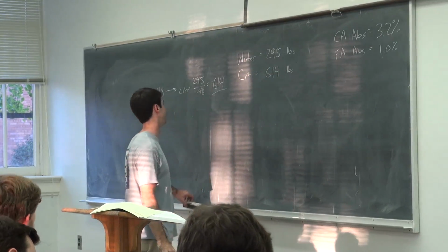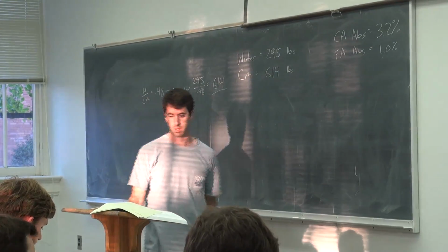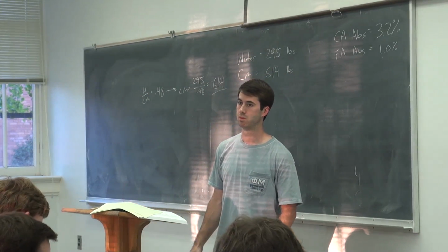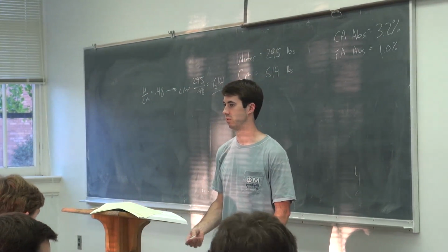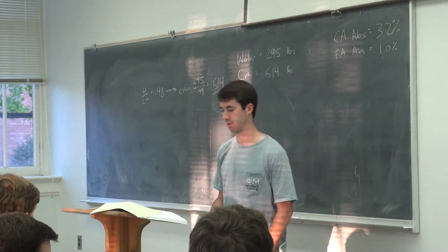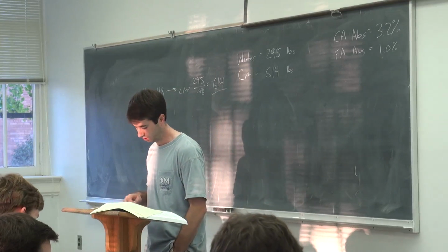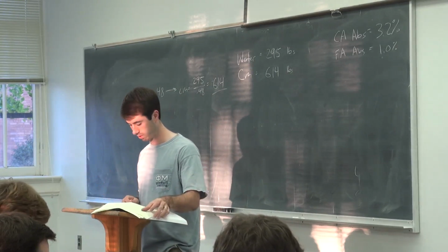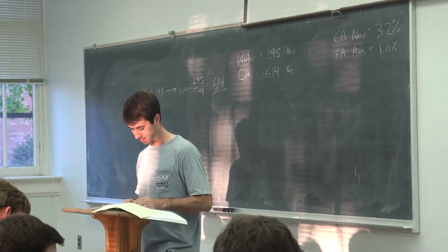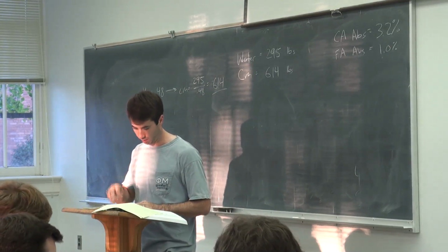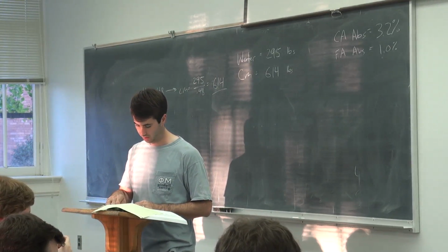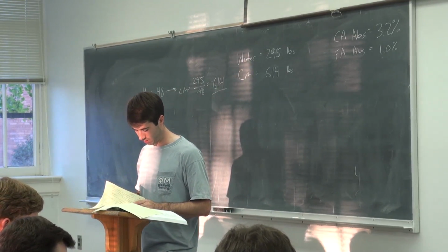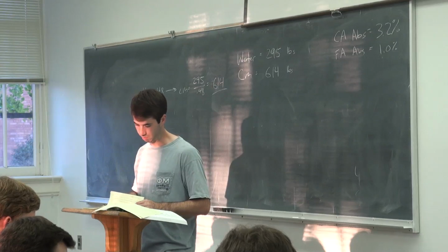All right. Then what? Fine aggregate? Coarse aggregate. Yeah, fine aggregate's always last. It's basically just a filler. So we take our fine aggregate properties and our coarse aggregate properties. We are given a fineness modulus of 2.85 and a maximum size of 1 inch, we'll say nominal max.